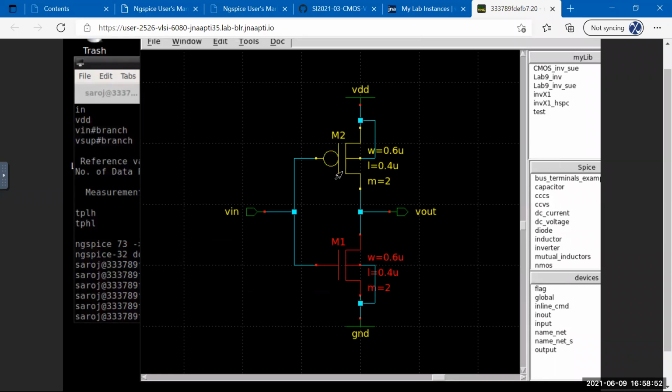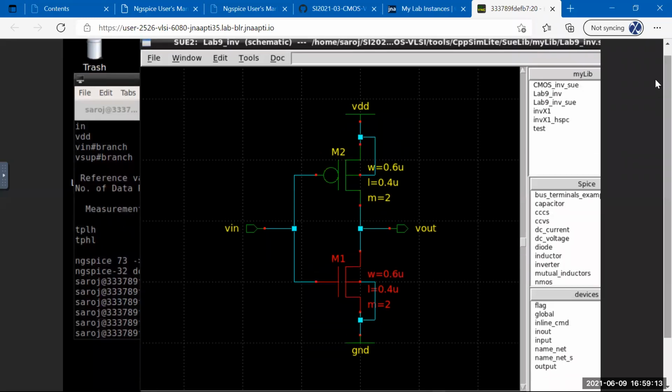And that netlist you saw is actually written in Tcl. We have written it in Tcl, and you see the symbol. So if you have a new technology, and instead of NMOS it's NP, and W is something else, you can write all that and create a new symbol and do all your schematics and simulate it here and so on.